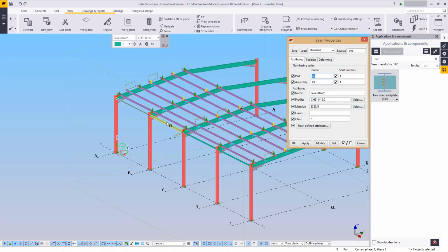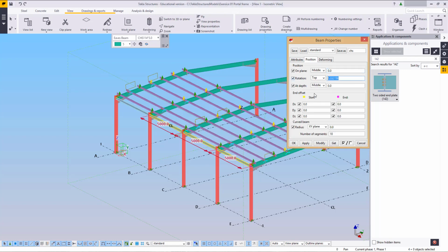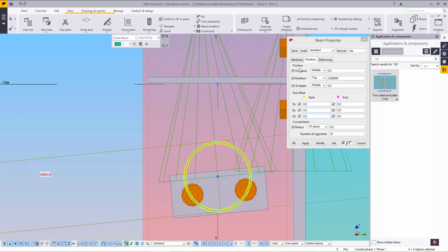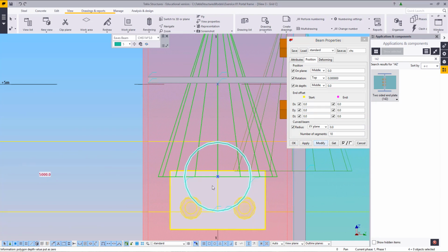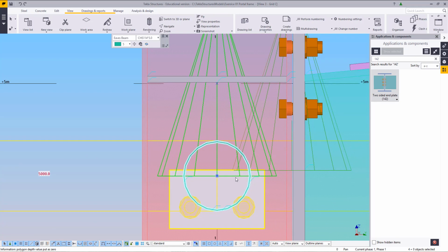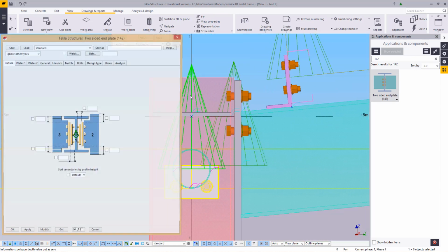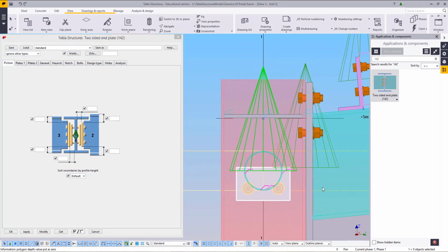After this, I'm going to open up the pipe, select all of them, go to position, and just make sure that my angle is 0. Now, this is a pipe. You won't be able to tell the difference, but the program does have a set top, bottom, and sides in order to work its stuff out. So, even though it looks the same to you, be aware that the angle does have an impact on the pipe.